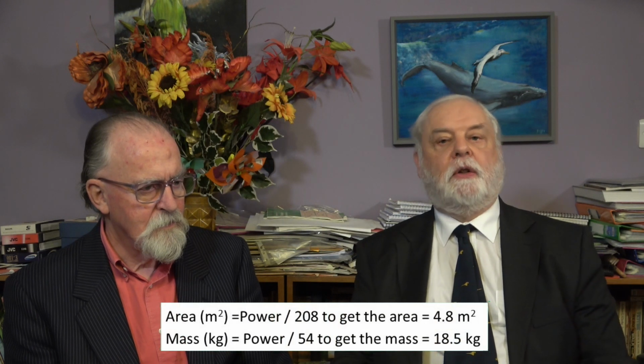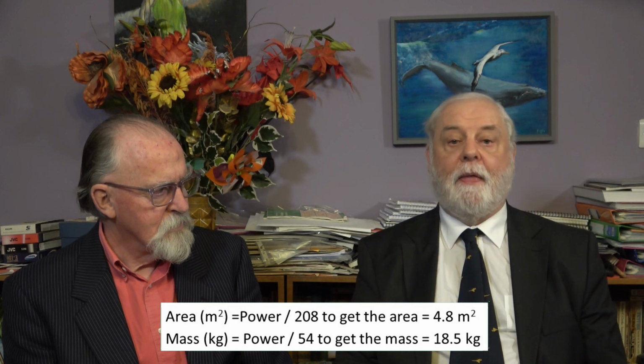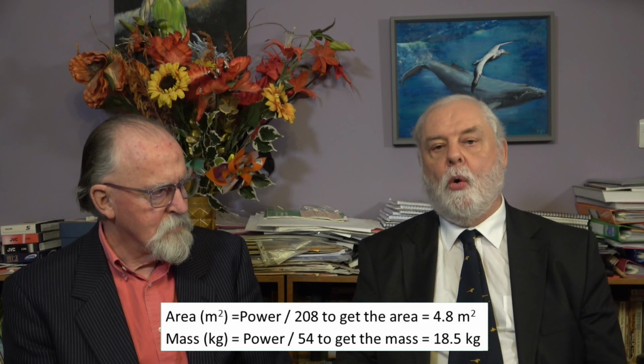If we have these relationships for all the important system parameters, then we can speedily produce preliminary design, feasibility, and preliminary system outline purposes. For example, if the function of a spacecraft power system is to provide 1 kilowatt of power using an array of photovoltaic cells, then we can use these relationships to give us estimates for the solar array area. It comes up 4.8 square meters, and the mass of 8.5 kilograms, all from the known power level. Another example is we can make a first estimate of the mass of a satellite structure as being 6% of the total mass it will be required to carry.